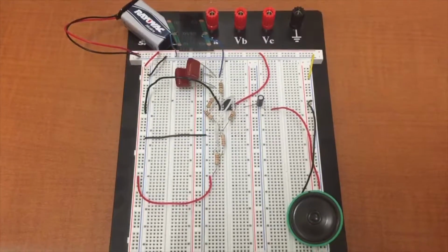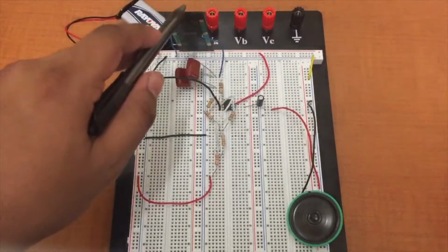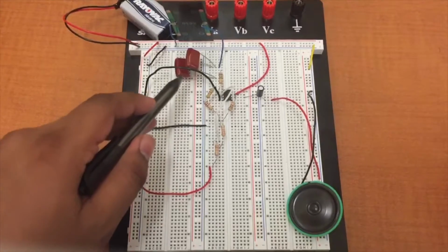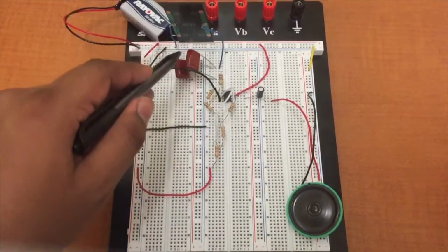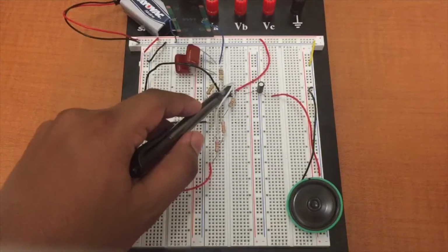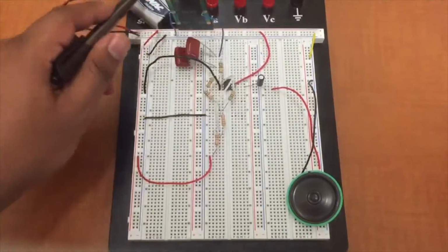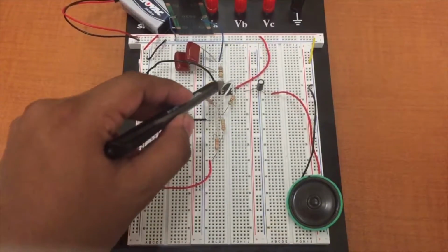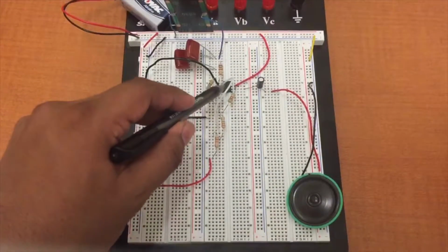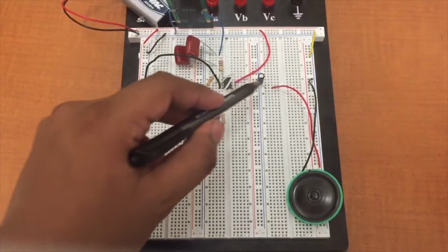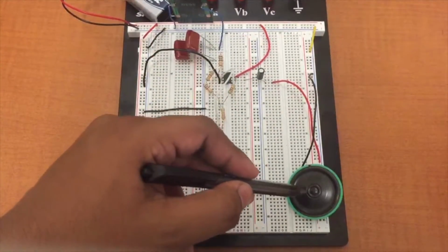So here we have the receiving circuit, which begins with a laser hitting this PIN diode, and the PIN diode is connected to two 1 microfarad capacitors, which are in parallel, which is then connected to a 100 ohm resistor, and then this goes to an op amp right here, where one end is connected to the 9 volt battery and the other end is grounded, and this has a 7600 ohm feedback loop. So this op amp is connected to a 10 microfarad capacitor, which goes through to the speaker and eventually creates the music.